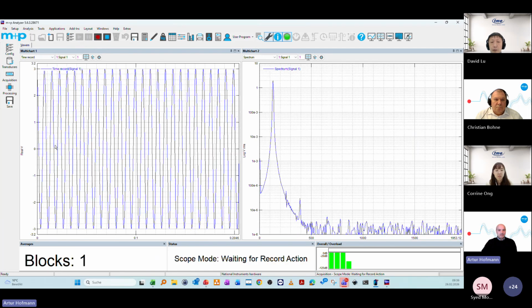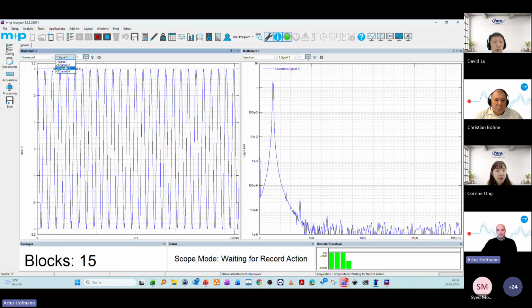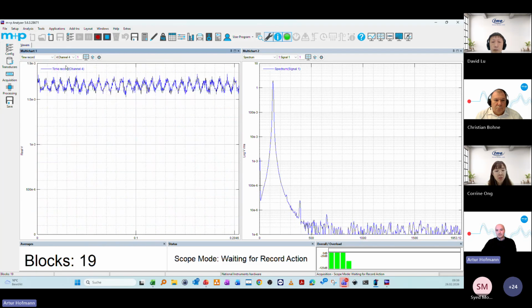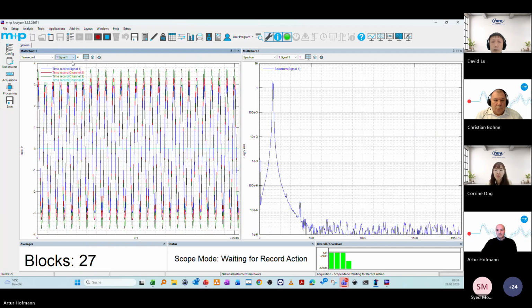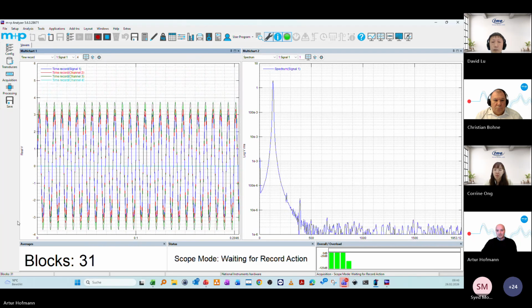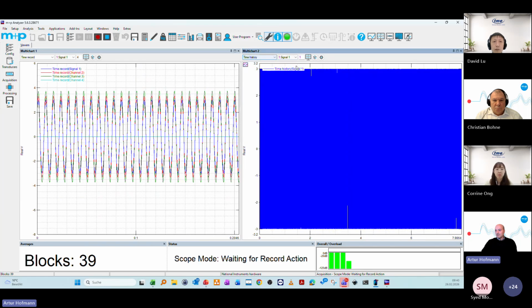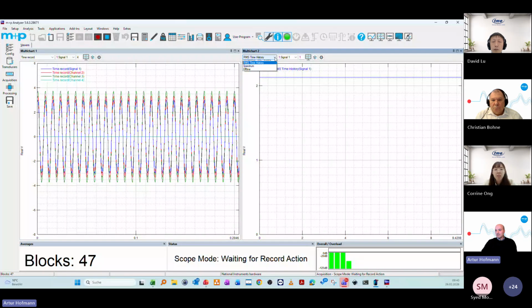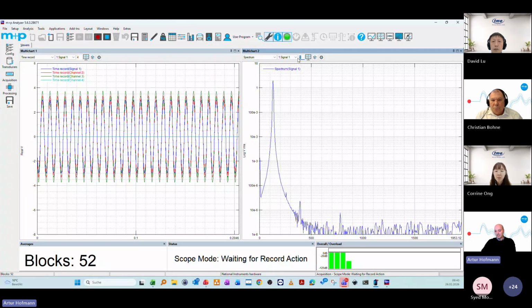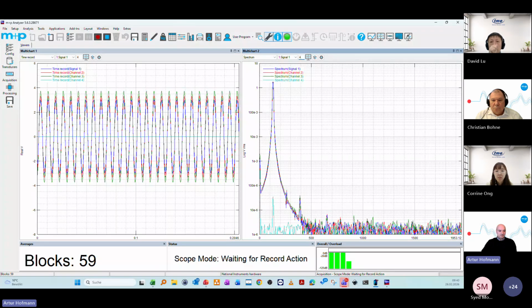So now you will see already the live signal from my signal generator, and he activated the time record, and you can see channel 1, channel 2, 3, 4. You can also activate all channels in one chart, of course. And here you can see the time history, for example, or the RMS time history, spectrum, and here the same. You activate the 4 channels.